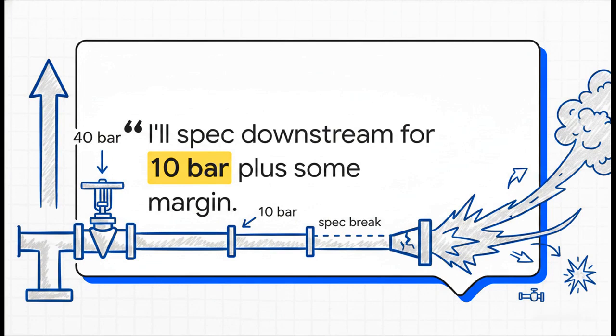If you're an engineer thinking this way, assuming the normal steady-state modulating outlet pressure naturally dictates the downstream piping class, you are falling into a massive process safety trap. A control valve dropping pressure from 40 bar to 10 bar in normal operation is just a momentary snapshot of an intentional, dynamically controlled condition. It totally relies on instruments working perfectly. That operating pressure tells you absolutely nothing about what happens when that dynamic control is lost.